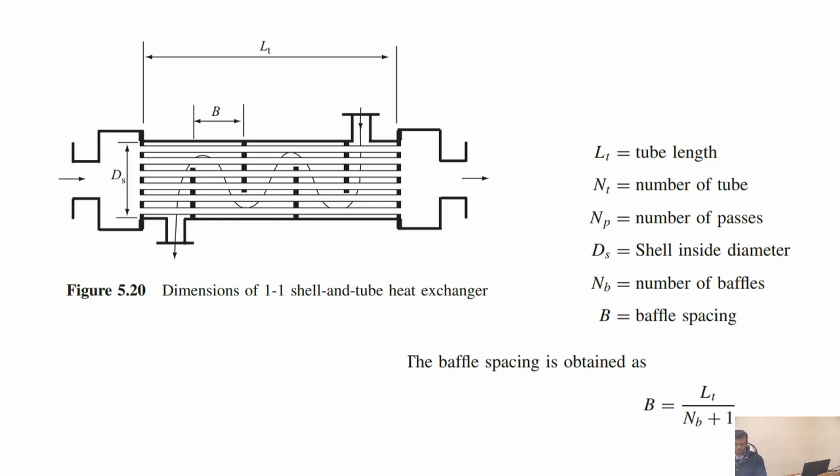And that area calculation will also depend on the overall heat transfer coefficient U, right? Because the heat transfer is proportional to the overall heat transfer coefficient. It's also proportional to the area and some effective temperature difference, right? We wrote in yesterday's class Q equal to U A, then some factor, then delta T LM, correct? So these things are all coming into the picture. Our purpose is that we want to get some estimate of that area and then distribute that area among these many tubes.